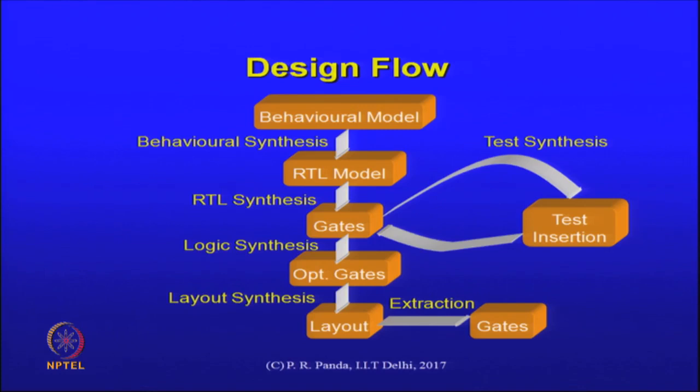Remember, at the system level that itself was not decided, but for a behavioral model of hardware, we go through a behavioral synthesis step to generate an equivalent RTL model. Then an RTL synthesis step takes us from the RTL model into gates. This is more structural, as we had seen, a structural netlist. This is where we may need to manipulate the design to insert our scan circuitry, the test related circuitry.